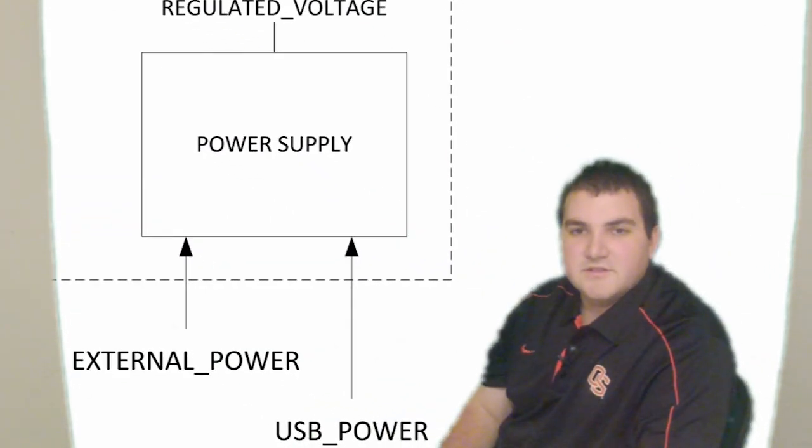The major functions of the power supply block are charging a battery pack and regulating voltage from a battery pack to power the robot. This means that there will be 2 subblocks, a battery charger subblock and a voltage regulator subblock. The battery charger subblock will take power input from either a 12-volt DC power adapter, which will be plugged into a US power outlet supplying 1 amp, or a USB port which provides 5 volts supplying 500 to 900 milliamps.